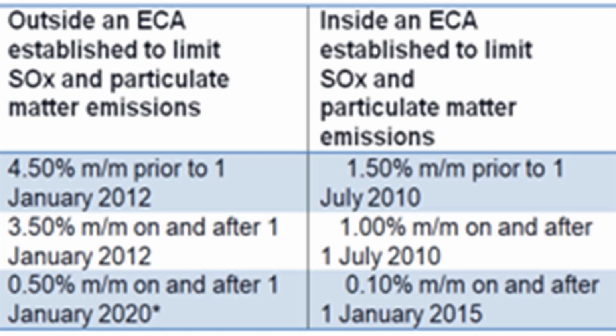So the regulations want that the sulfur dioxide that is emitted in the atmosphere, mass by mass, is curtailed to the provided limits. These limits have changed from time to time. So the regulations which apply in respect of emission of sulfur dioxide and particulate matter can be considered as the regulations which apply outside the ECAs, that is emission control areas, and the regulations which apply inside the emission control areas. And once again, the control can be done by two methods. One is by primary methods and the other one is by secondary methods. Primary method means the fuel that is supplied to the ship.